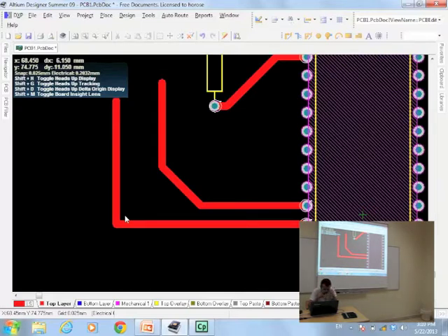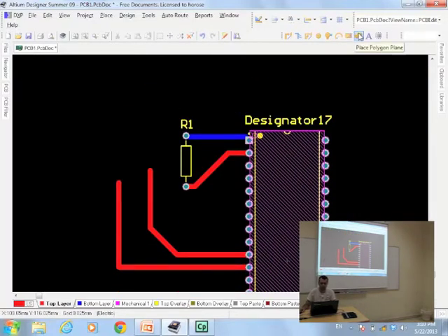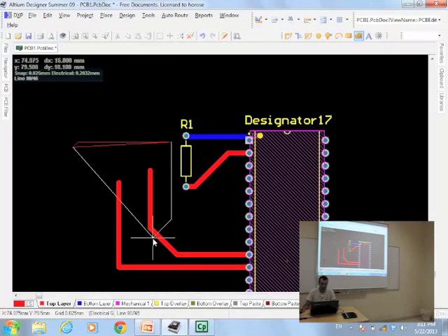If you see some planes under my PCBs, they are called polygons, and I cover some part because those are very noisy circuits. They are for SMPS and this kind of switching thing that generates lots of noise on the line. So I need to protect my things, but most of you don't need them. But sometimes, if you want, there are shapes like these polygons, you can bring them on your PCBs if you want to cover some parts.